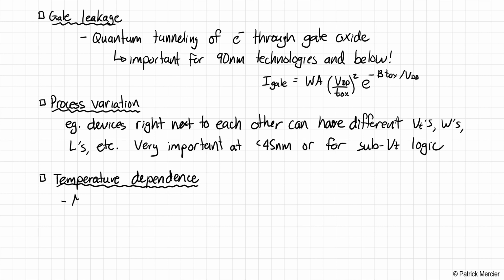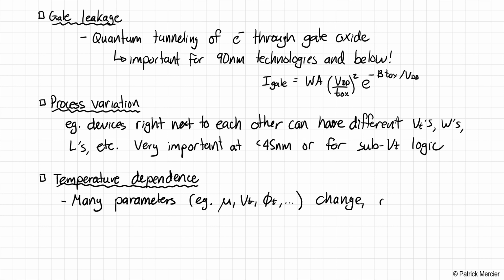There are other parameters that are temperature dependent, so we can say many parameters, for example, mobility, threshold voltage, thermal voltage, etc., change, often, unfortunately, non-linearly with temperature.